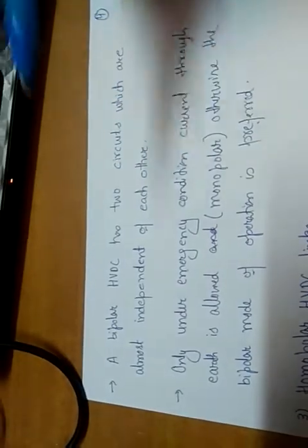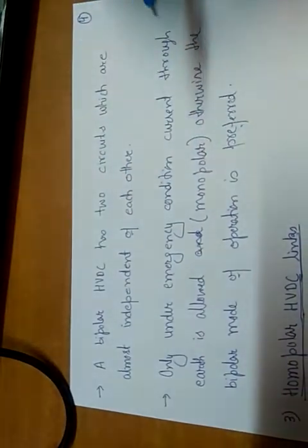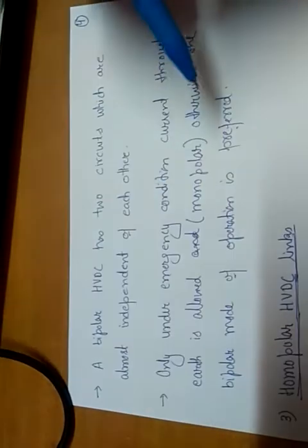So let me write that. A bipolar HVDC has two circuits which are almost independent of each other. Both circuits operate independently. Only under emergency condition is current through earth allowed. Otherwise the bipolar mode of operation is preferred.